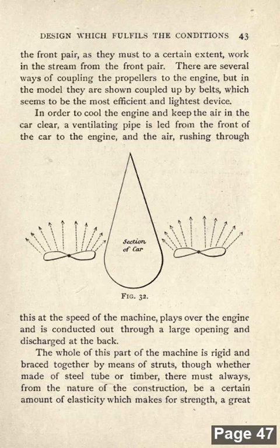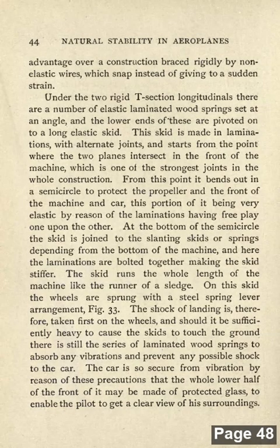The whole of this part of the machine is rigid and braced together by means of struts, though whether made of steel tube or timber, there must always, from the nature of the construction, be a certain amount of elasticity which makes for strength, a great advantage over a construction braced rigidly by non-elastic wires, which snap instead of giving to sudden strain.